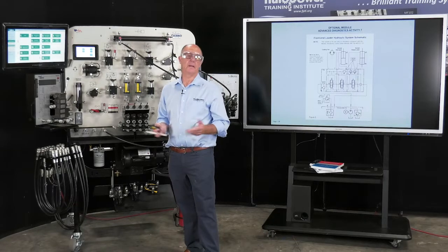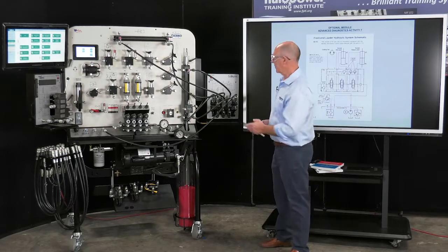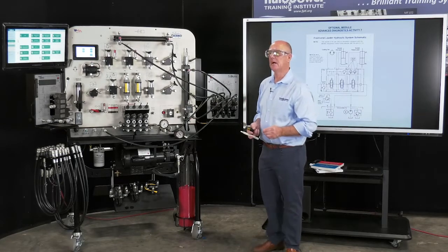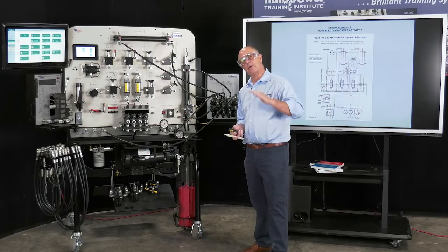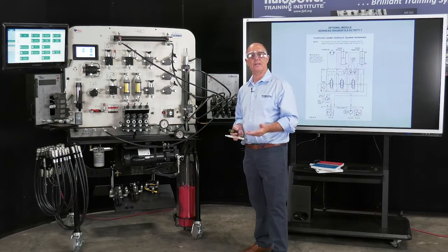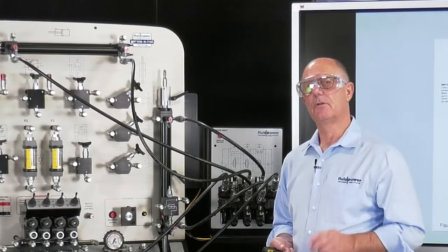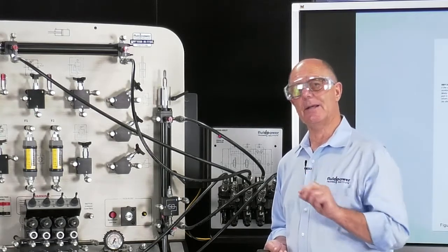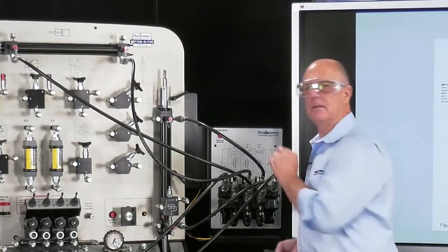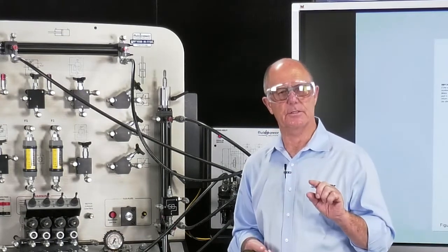In other words, let me give you an example. Using this valve, before I show my students how to test a valve, a mobile valve, I ask them this question. Have you ever had any reason to believe that you had a vertical downdrift on a cylinder and the oil was leaking into the directional control valve? And when they say yes, I ask them what they did. They said they replaced the valve. So without exception, in 20 years, I have never had anybody tell me that they were able to go and find the leak in that valve. They found the valve was leaking, but they never pinpointed the leakage.